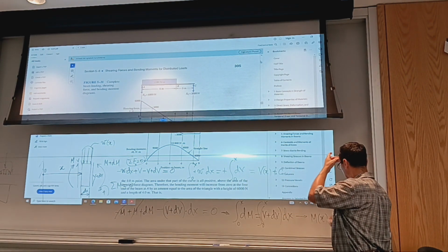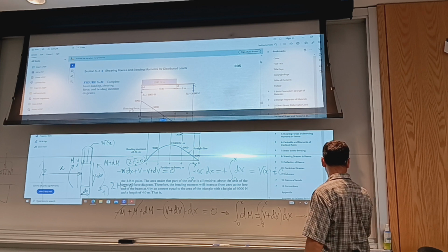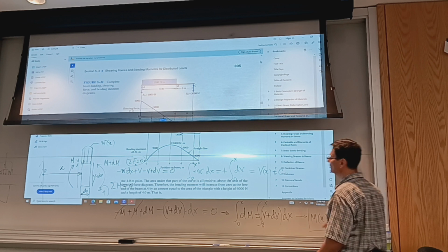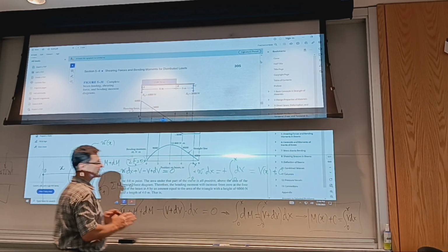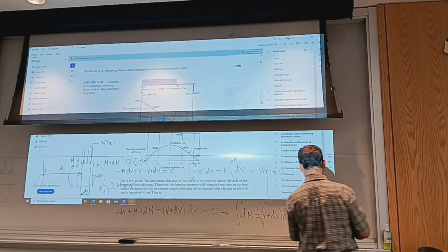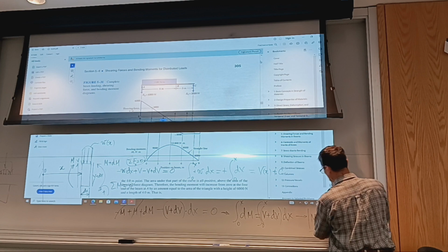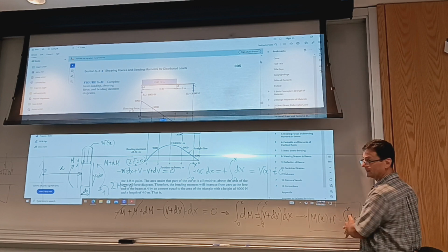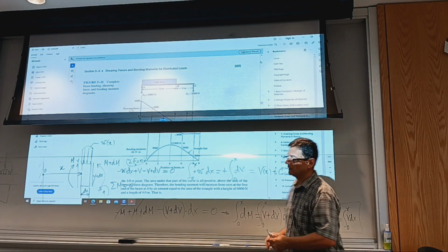Okay. So yeah, this is the equation that relates moment to a change in shear. So this is nothing but, I integrated from 0 to x, but I can integrate between 2 points on the diagram. So if I do, I'm just going to get what is called the moment change over the diagram equals the area under the V curve. Does it make sense? All right.